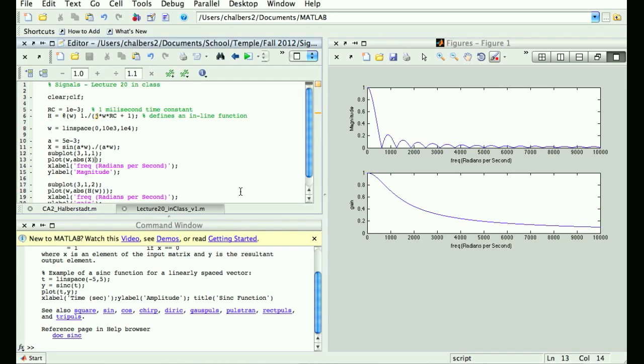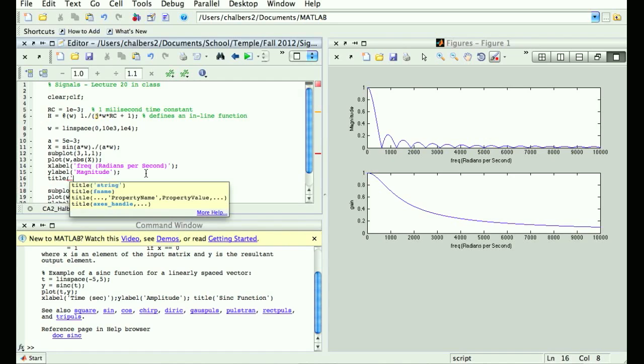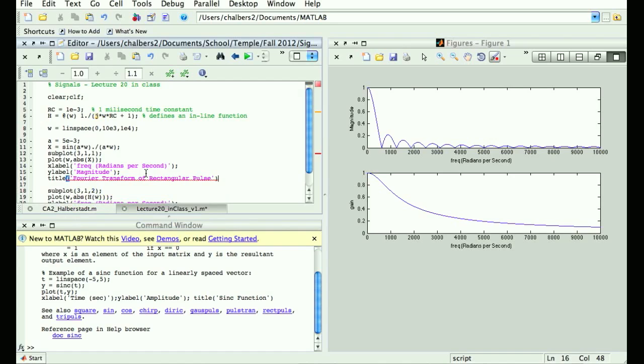So what am I going to do with those two functions? Remember, my whole goal is to get the output for an arbitrary input. So there's the Fourier transform of my arbitrary input. There's the transfer function in the middle. So what does the formula say I'm going to do to those now? X times, where is it, H? The formula tells me specifically that the output Fourier transform equals the input Fourier transform times the transfer function. That's what it told me. Isn't that right? I mean, we derived it.